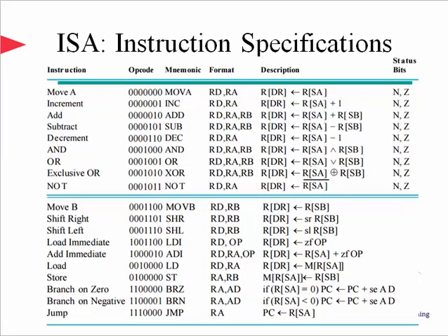After covering the program counter and its details, let's cover the instruction specifications with regard to the instruction set architecture. Alright, so here's the complete description of the instruction specifications based on the various possibilities of the opcode section. If you look at the opcode, you will realize that you can perform a lot of different instructions by just changing the 7-bit long opcode section of the 16-bit long instruction word.